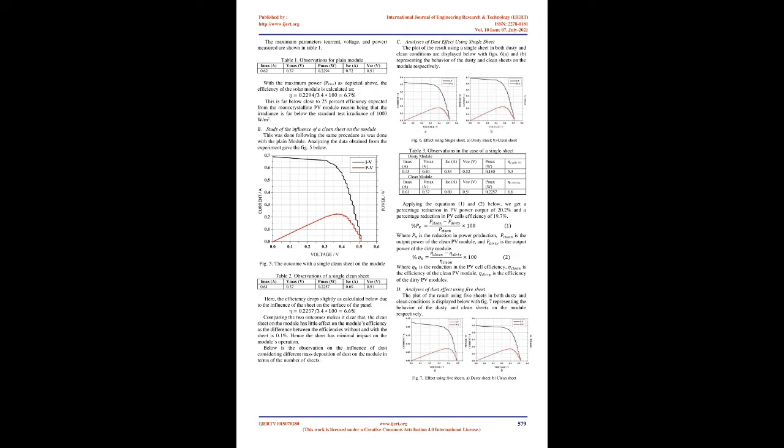The solar cell and the sensor field must not be shaded during the measurement. An irradiation unit is used to irradiate the solar cells unit with artificial light incorporating a 12 V/50 W halogen lamp. This was chosen with the assumption that, at a distance of approximately 10 to 15 cm from the halogen lamp, the same value is achieved as that which is achieved during the measurement of the irradiance of the sun